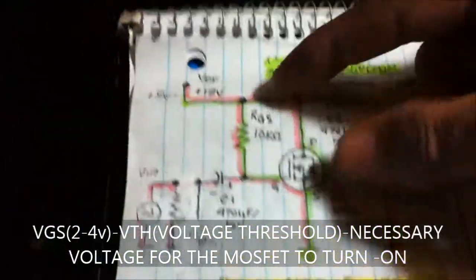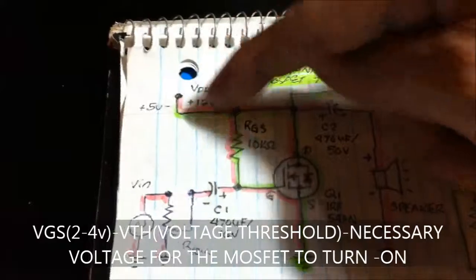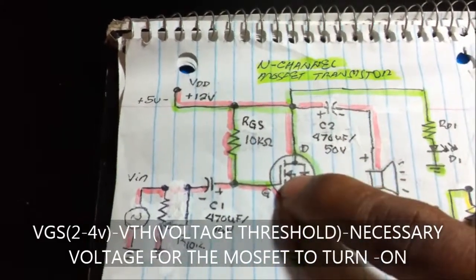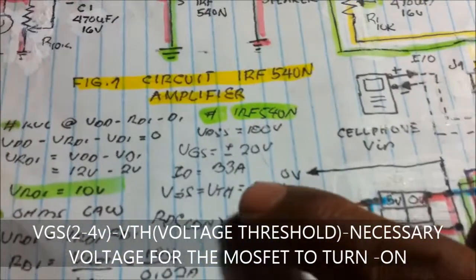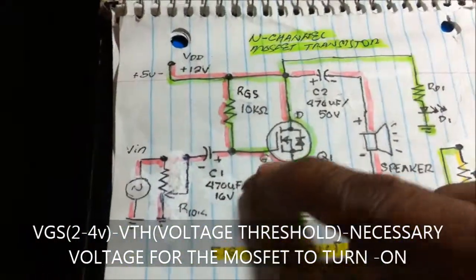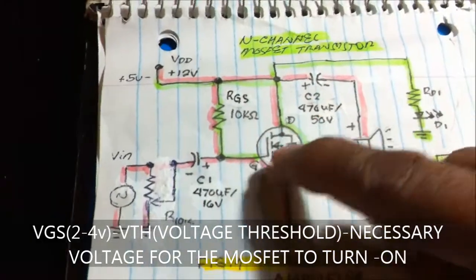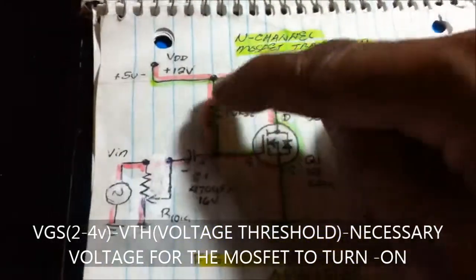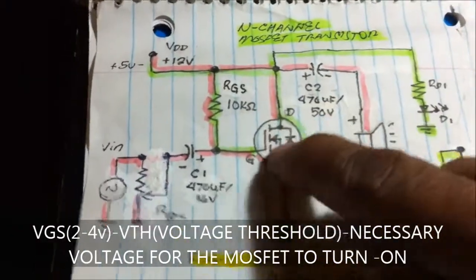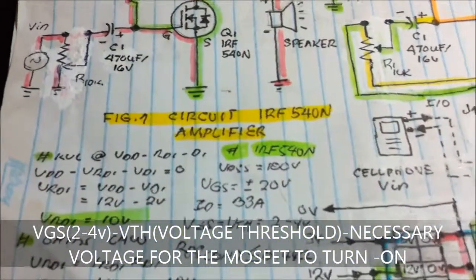Well, VGS is the maximum voltage you can apply to the gate, while VTH, voltage threshold, is the minimum voltage you can apply to the gate to turn on the Mosfet.